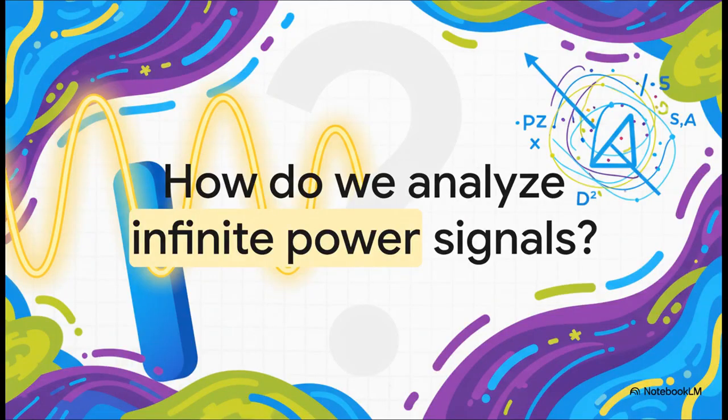So up to this point, basically everything we've discussed regarding the Fourier transform really relies on the signal having finite energy, which just means the signal eventually ends. But what about signals that never end? What about a pure continuous DC current or an endless sine wave? I mean, these are infinite power signals, and frankly, the standard Fourier transform math actually breaks down when we try to analyze them. So how on earth do we bridge that gap?